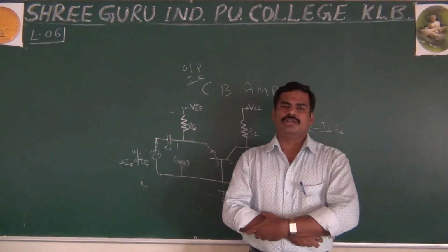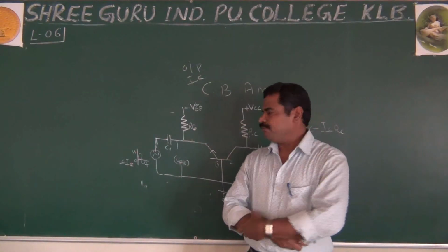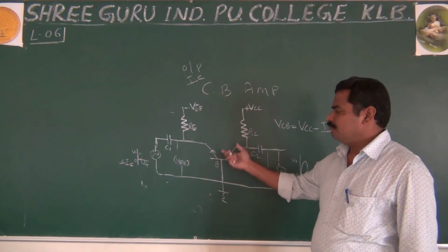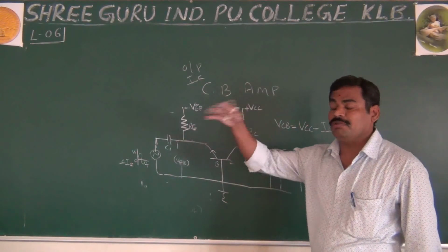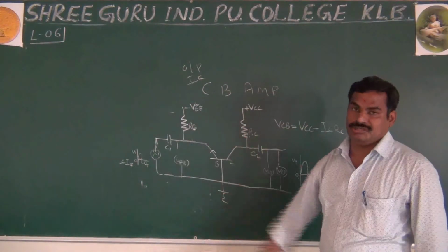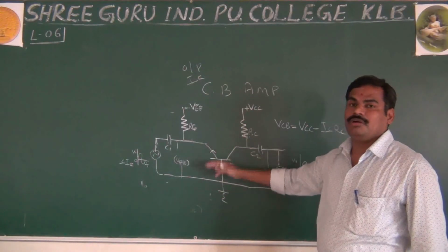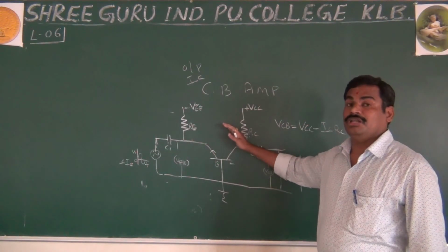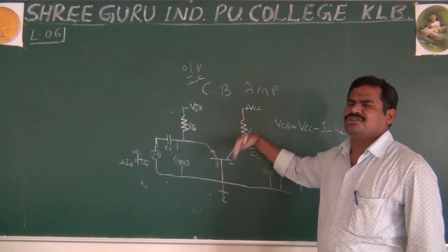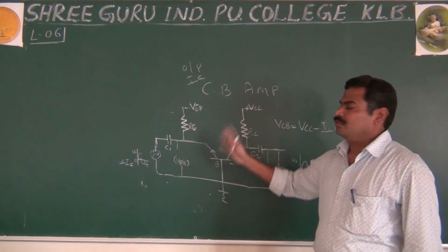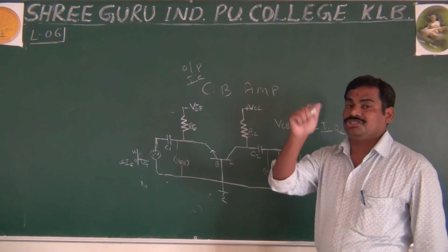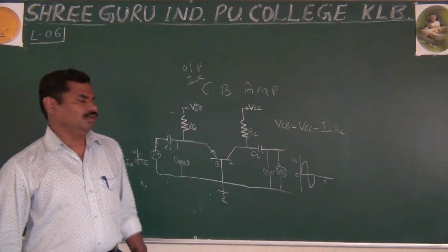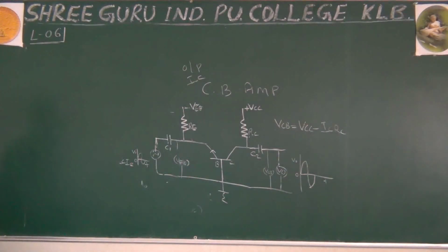The most important drawback, especially since we are going for amplifiers, is that this common base amplifier is not amplifying the signal, but it attenuates the signal. It is not increasing the current, or not amplifying the signal, but it is attenuating the signal. And you may ask the question, why, sir, is it attenuating the signal? Because as I said here, your